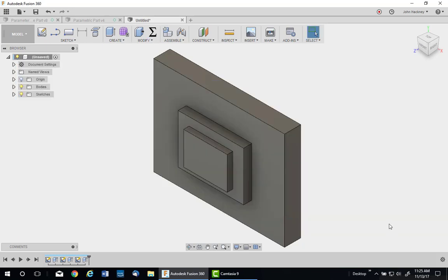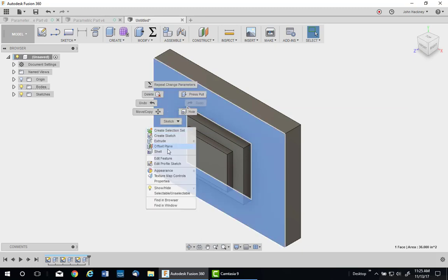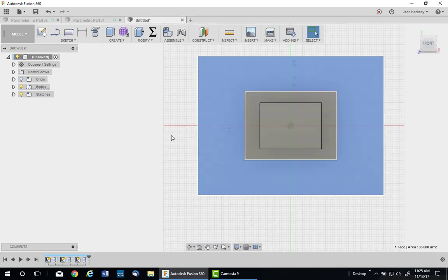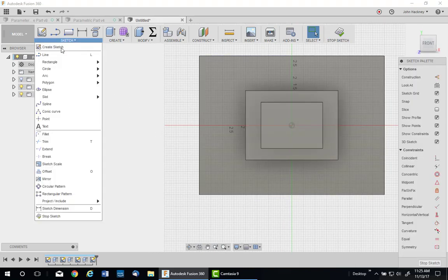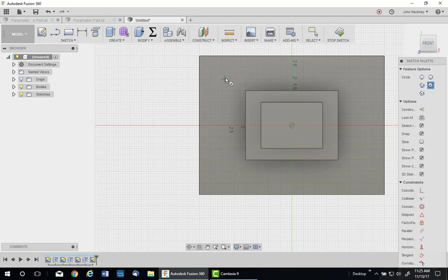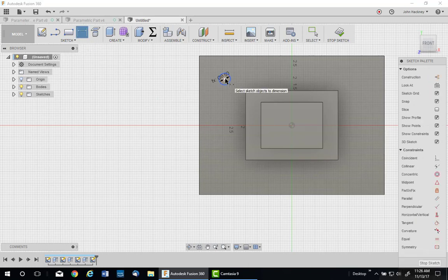Now that becomes available just like the favorites. So if I put a sketch up here, and I put a circle, diameter, I'll put it in here somewhere. And now if I hit D, notice it picks that up, even though it's not the first letter, it still picks it up. Circle diameter again, hold your cursor steady and lock it down. So you can pick up parameters now the same way.